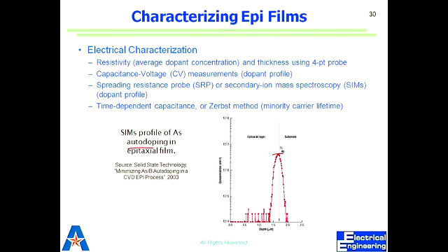We can cut the wafer from the side and measure from the side. Use the probe along the depth. For instance, cut the wafer and have a probe which goes down on the side. Measure the resistivity. Tells you how much is the doping and what depth, right?